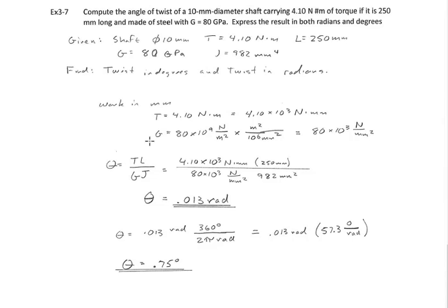We're going to substitute that into equation 3.11, where theta equals torque times the length divided by the modulus of rigidity times the polar moment of inertia. Okay, so I set all my values in here. Remember to write down your units because it's very important.